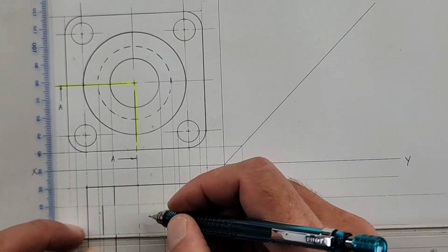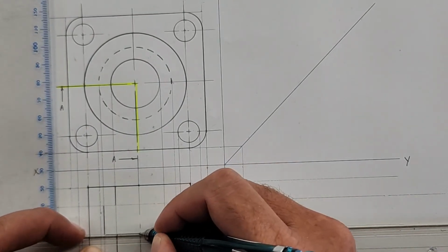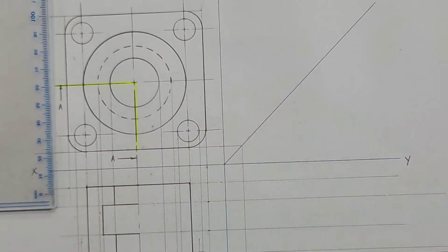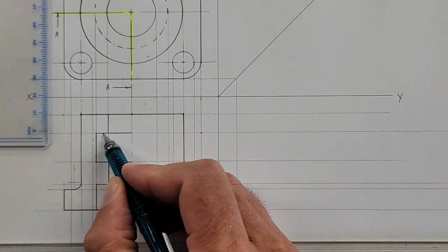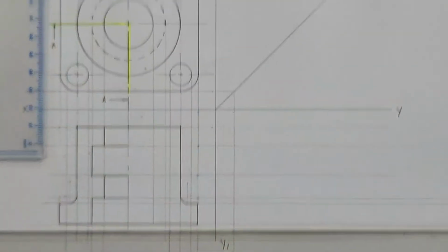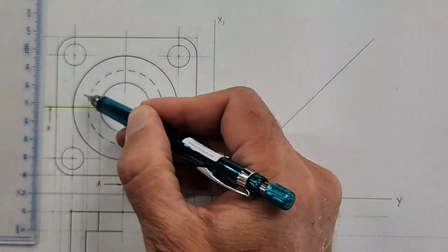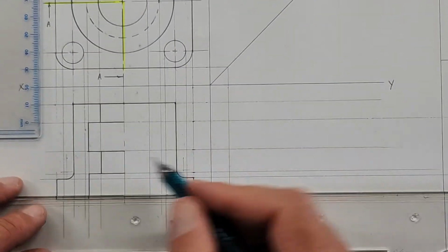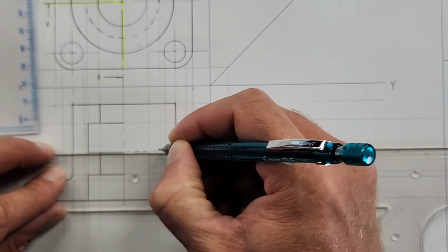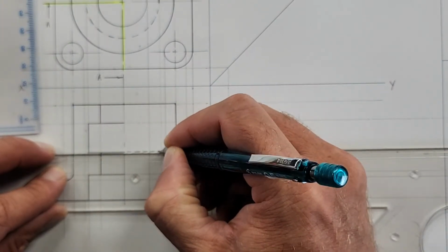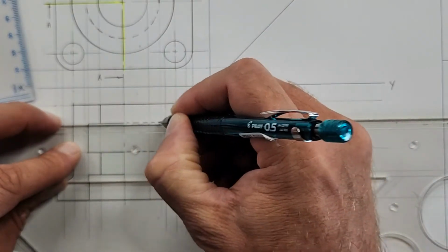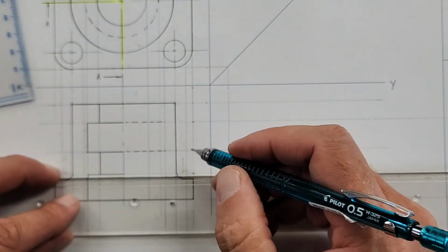Okay, why do I draw this line all the way through to the center? Why do you think? Why does this line go here? Because on the inside there is a line running. So my hidden detail will continue on this end. There's my hidden detail, that continues. Can't ignore that. Because remember, this side's not sectioned.